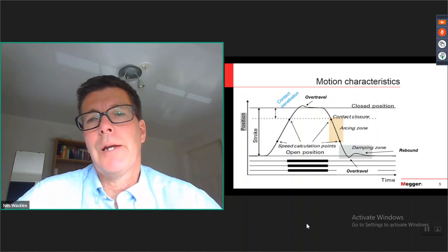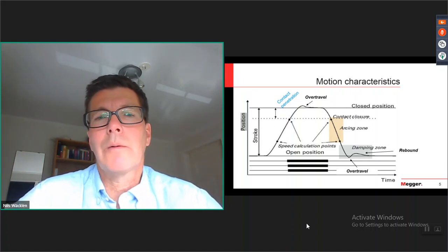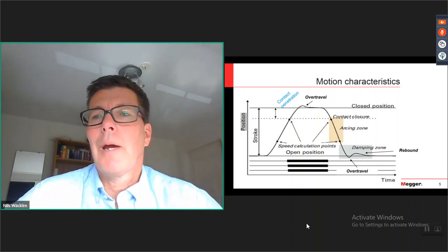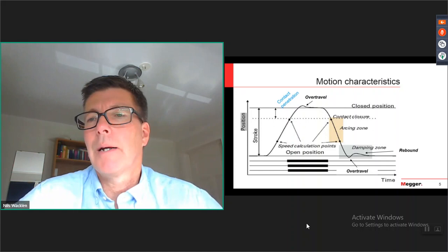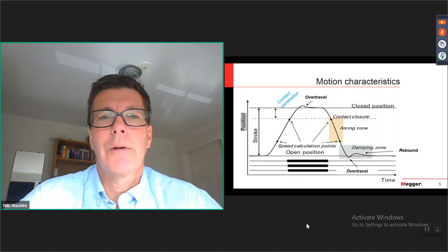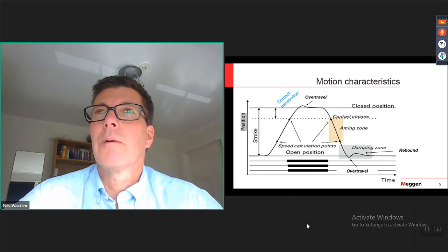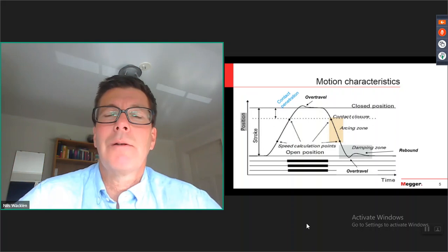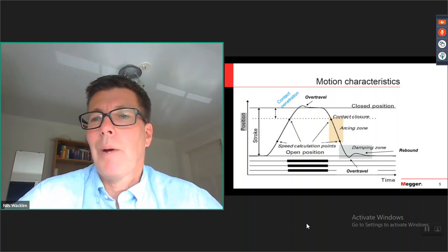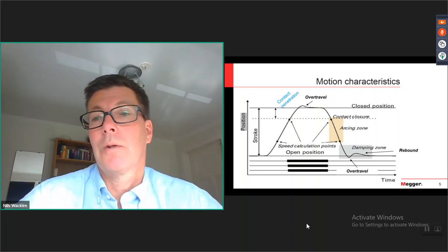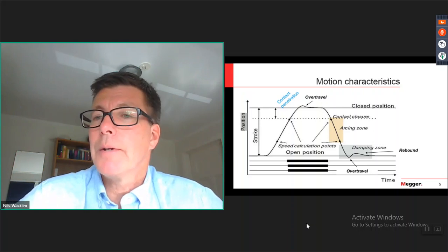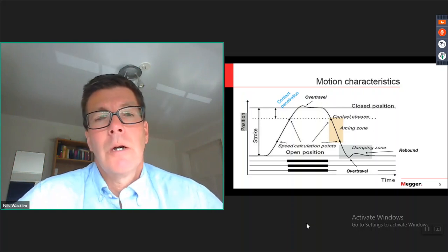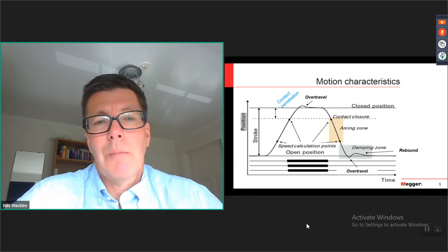But it's all about trending. If you see a behavior that you have not seen before on a particular breaker, then you should of course ask what is the reason for this. It can be a loose arcing contact, for instance. That happens also. So that's the electrical bouncing.